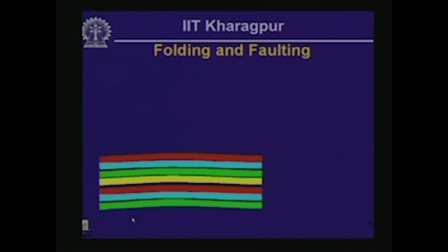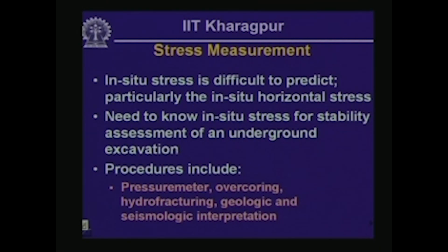Now what we could also do is pump water in within the joints and pressurize at high pressure, and this process is going to actually start opening up the joints when the state of in situ stress is overtaken by the pressure in the fluid that is being pumped in.